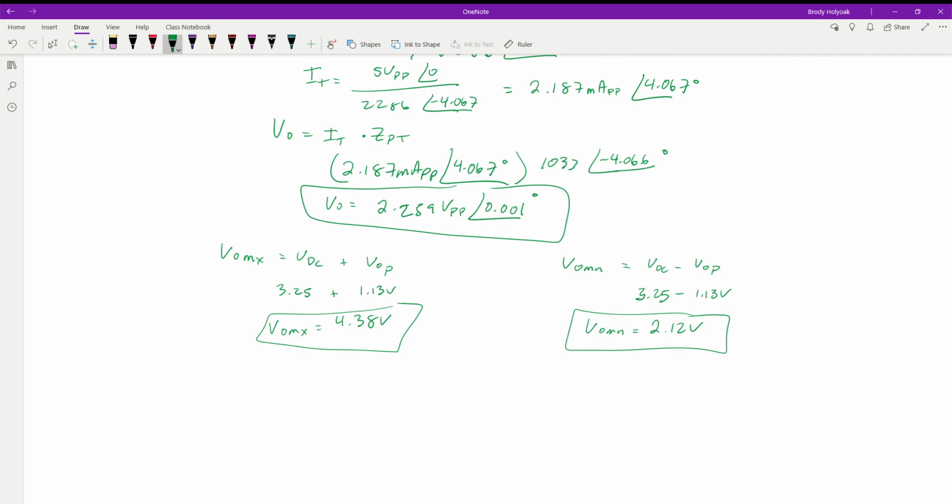But either way, like I said, this is how we're going to go through. And then also, if you notice, our angle is 0 degrees. So at our midpoint frequency, or really anywhere between our FC1, FC2, it should be getting close to 0 degrees. So we're going to start at 45 degrees on FC1, and that angle is going to get less and less until it hits 0. And then at this point at our F mid, that's going to be the highest point where we're going to be at 0.